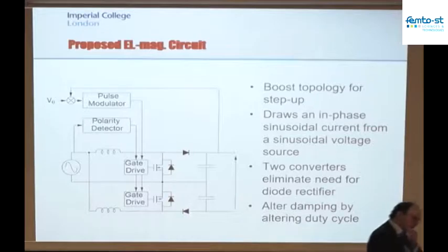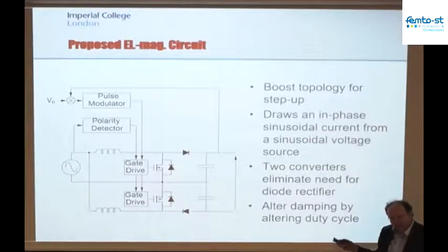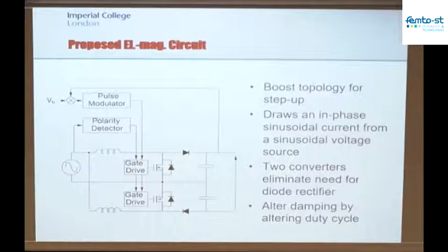So typically what we tend to see now, and I've got more information on these circuits in the next slideshow, is that it's possible to build the control circuitry for these devices running off maybe 10 microwatts, that sort of order. Now, if your overall harvester output is going to be less than 10 microwatts, then you wouldn't be able to use a sophisticated control scheme.